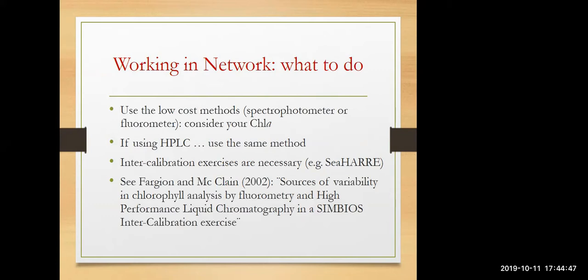In general, it is recommended in these cases that we use the low-cost methods, spectrophotometers or fluorometers, and of course, considering your range of variability in chlorophyll-a concentration. If my study site is characterized by high chlorophyll-a concentration, I can use a spectrophotometer without any problem. But if I am working with very oligotrophic water, I will have to use at least a fluorometer.